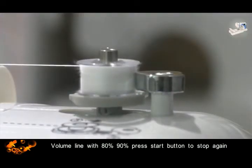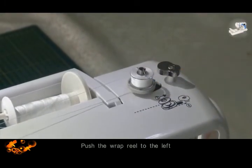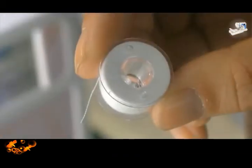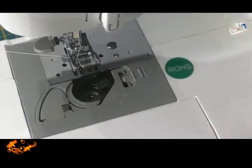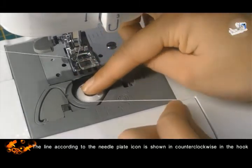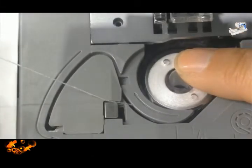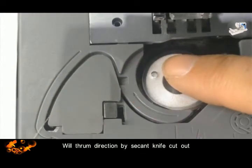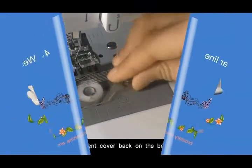Wind the thread until it is 80%, 90% full. Press the start button to stop again. Push the winding reel to the left. Take off the bobbin. Shear the thread. For the bottom thread, open the transparent cover. Place the thread in the hook counterclockwise, according to the needle plate icon. Pull the thread end in the direction of the cutting knife to cut it off. Put the transparent cover back on the bottom thread.